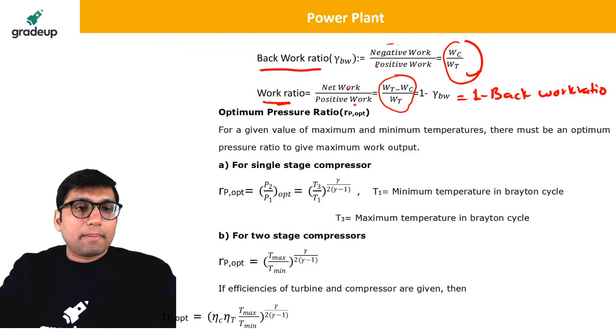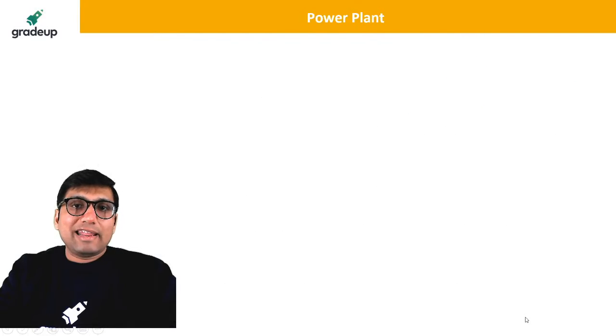The simple practical example, Harshit, is, you know that isentropic process is an ideal process. It is not a real process. In the real application, there will be some friction. There is no possibility that in a mechanical component like compressor and turbine, there is no friction. There will be some friction. And because of the friction, the compression and expansion are never isentropic in the practical situation. So in the practical situation, you have to take the compressor and turbine mechanical efficiency.